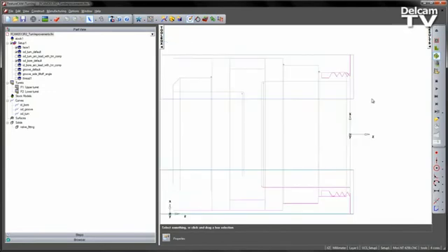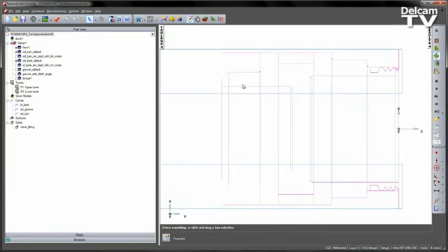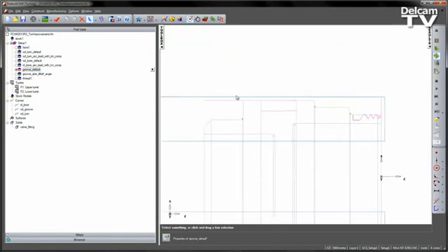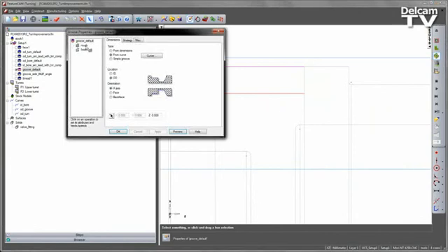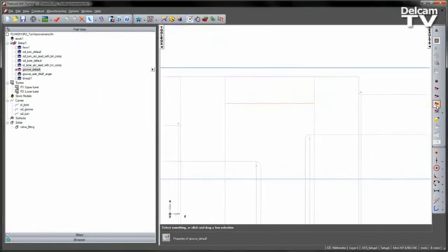The other enhancement we've added is the ability to control the withdraw approach from our grooving operations. Let's again go to our groove default operation, preview this toolpath. So note the grooving tool comes in, cuts to depth, moves across, cuts to depth. It is at this point where the tool is retracting up and it's skimming the material it's just cut into. There is nothing we can do about the first pass, but the subsequent passes we now have enough room to clear the tool backwards.